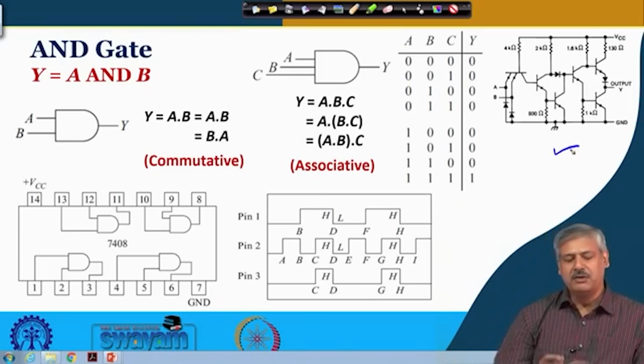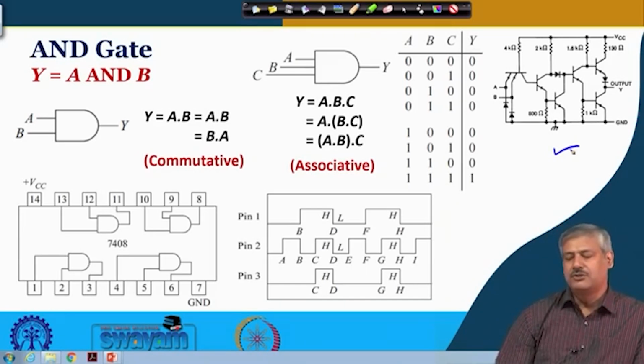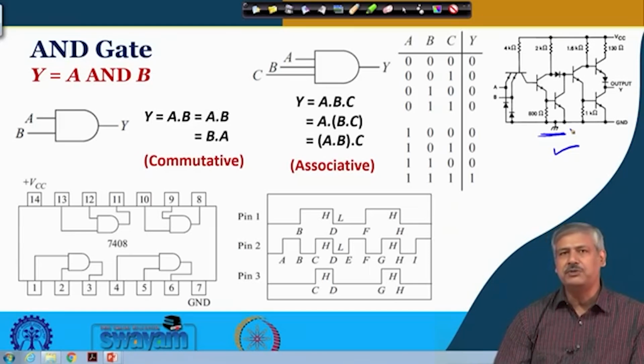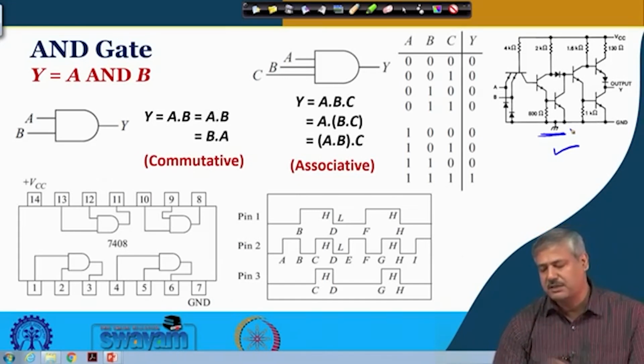And remember, when we talk about the circuit-level design of an AND gate, it is not a NAND gate with a NOT gate put after it. In a NAND gate circuit itself, an inverting transistor block can be put, with some associated additional circuitry, by which you can get NAND and NOT together, giving the AND operation. That is from the Texas Instruments data sheet, from which the circuit has been shown.